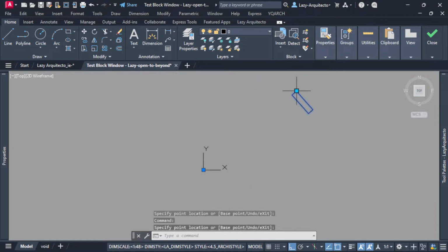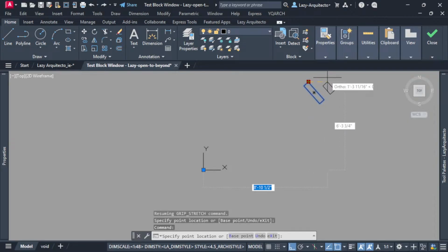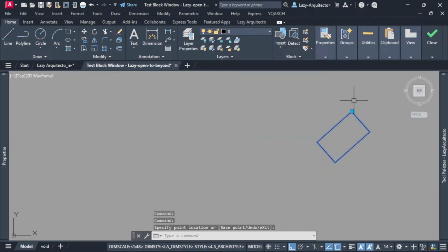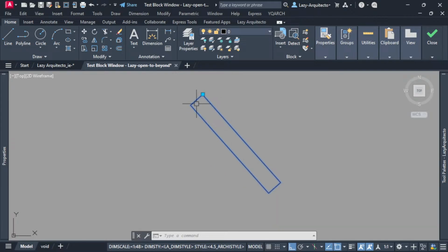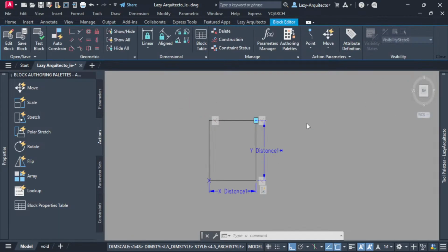We're keeping the four-sided rectangle shape all the time, but somehow it's still rotating and getting far away from our base point. So that would be a problem. So now we don't need a perpendicular constraint anymore, because you see that the four corners are nice and 90 degrees. So, but we need a different constraint.